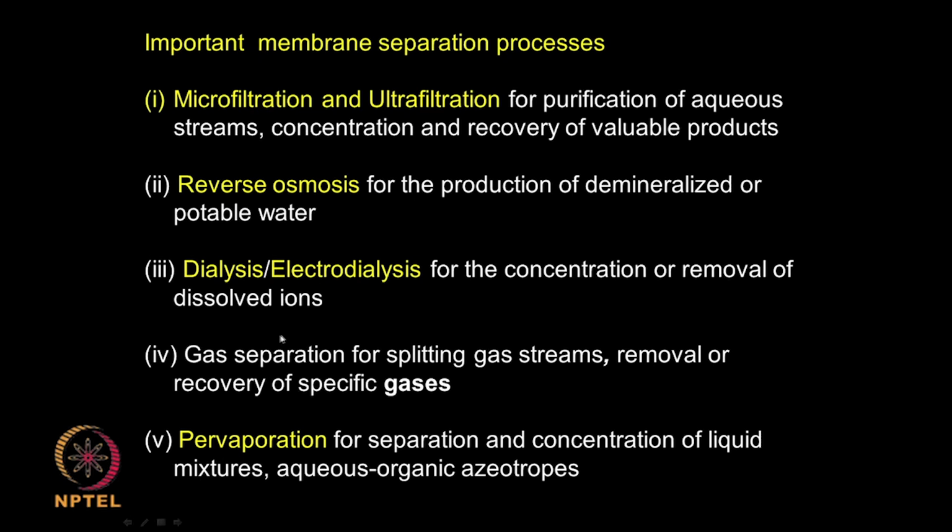For separating gases, if I want to separate gases of various sizes, then we can use membranes. Pervaporation is another technique where we can separate and concentrate liquid mixtures. Suppose you have water and an organic. I want to remove the water present, even the minutest amount of water can be removed using this type of technique. Especially this is very useful if you are concentrating fruit juices. We can't really heat fruit juices in a distillation column because they may get charred. So, we can use this type of technique called pervaporation.